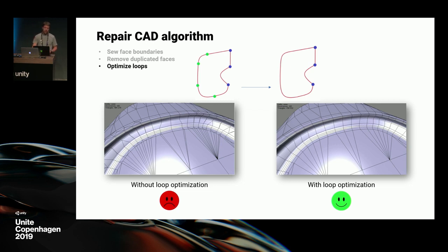Since each curve is tessellated independently, the tessellator will generate one vertex at each extremity. So merging these curves allows a better spreading of edges on patch boundaries. Now the model is ready for the tessellation process.